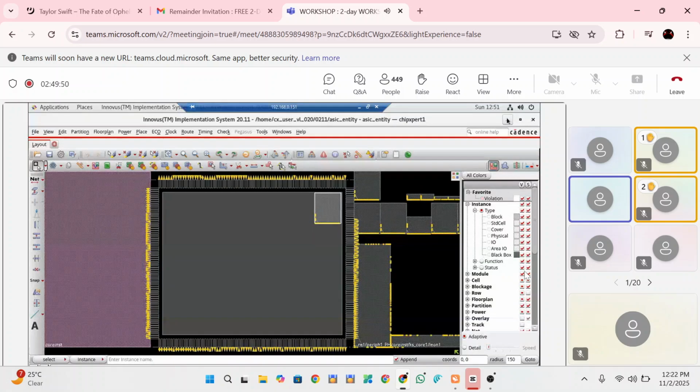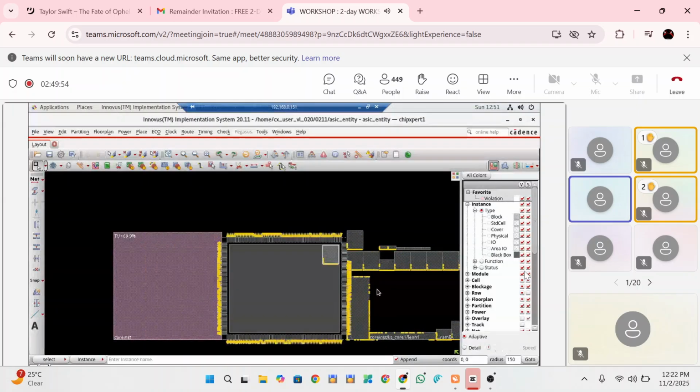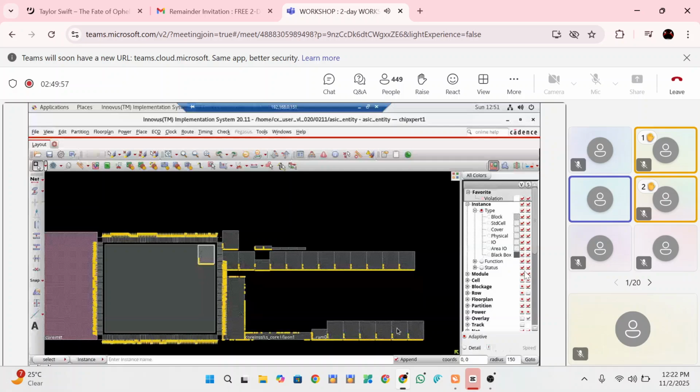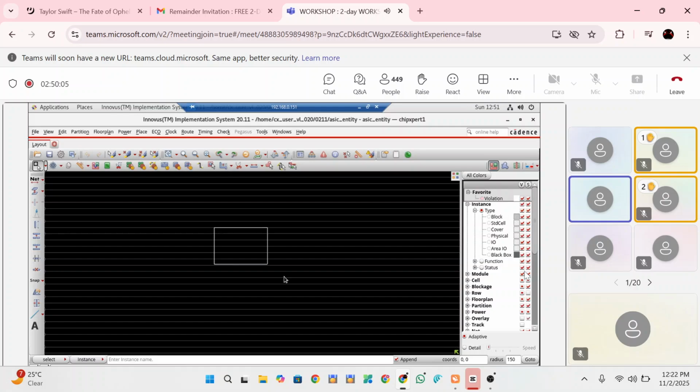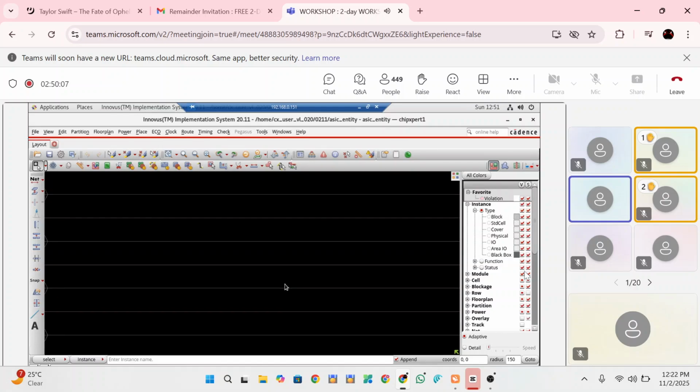What you see on the right side: they should not overlap. They should have a proper length. They should be sitting on proper rails. Can you show the follow pins, those rows? Can you zoom in? This is where the very small standard cells will be placed on this row. That is where your gate is going to be placed.